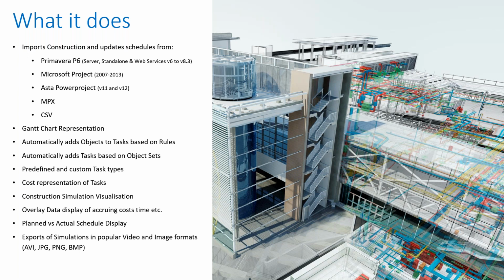It also produces a Gantt chart representation of the schedule once it's imported into Navisworks. It then allows us to automatically add objects to tasks, and we do this based on rules. It automatically adds tasks based on object sets, so if we don't have the tasks, we can create them from the geometry, the other way around.